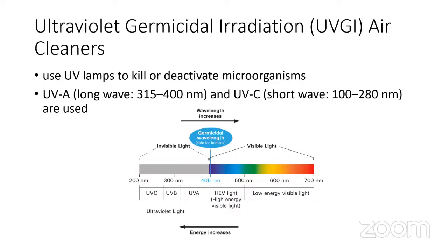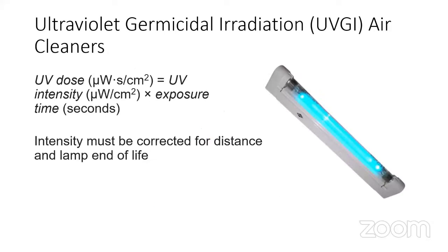Coming to the next slide. The lamps used for surface disinfection are normally located in the air duct of an HVAC system, and they would be normally kept perpendicular to the airstream for maximum impact on the air which flows through the duct.